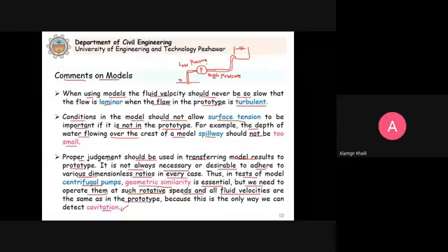They move from low pressure to high pressure. So when they reach here on this side, what happened? Let me draw. Let's say we have this metal surface. This can be the blade of this runner, and it can even be the pipe on this side here. So what happened is that this bubble sticks to this surface here. This is now the bubble.